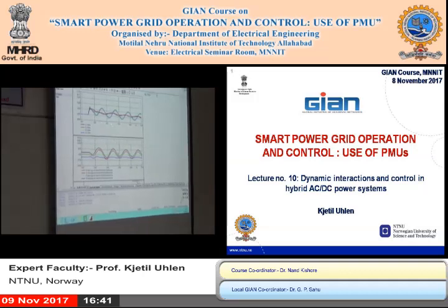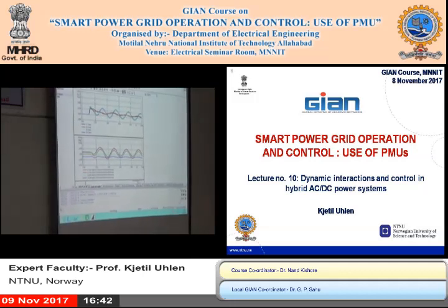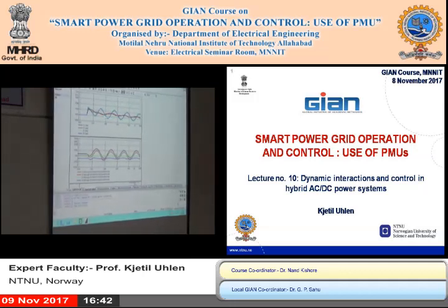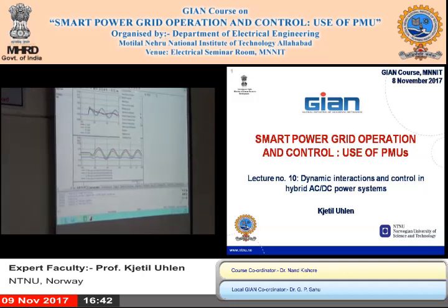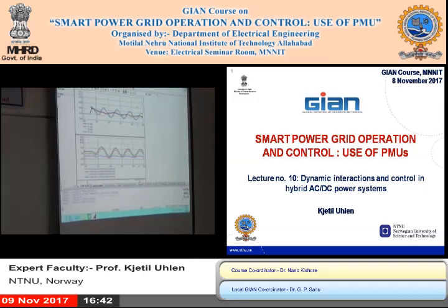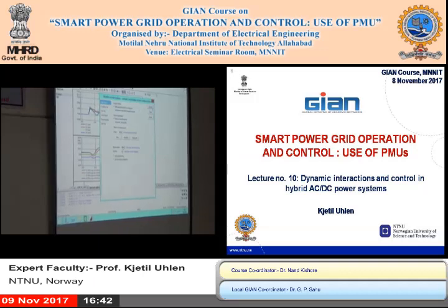And here it's a little bit clearer that the speed deviation is highest for generators 3 and 4, and that there is something going on between generators 1 and 2. And then to investigate that further, following what we had talked about earlier, we go to modal analysis. Do a restart if necessary.